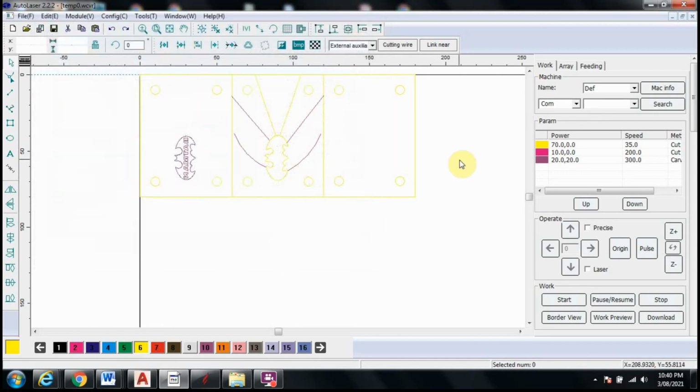So that's how you will save it if you want to keep it. Now, one thing to note when you save things and then open them again several days later: if the cut settings have been changed on a previous user's use of the software, then the cut settings will stay the way that person changed them. Even though you've saved it, they won't change back to what you saved them as.